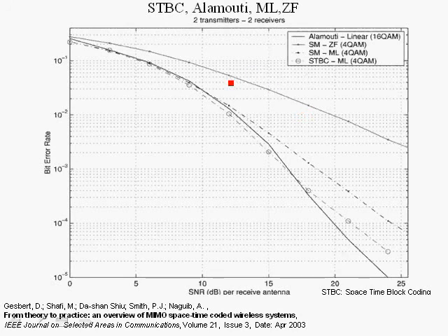Now obviously, as the signal to noise ratio increases, the bit error rate decreases, but not very rapidly in the case of the zero forcing MIMO equalizer. So each stream is using 4 QAM, so that the overall throughput is the combination of the 4 QAM streams. So we're using two spatial streams.